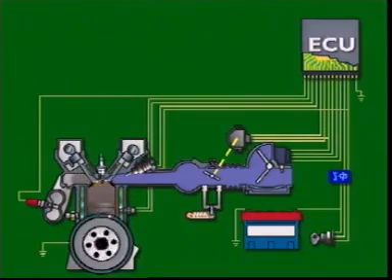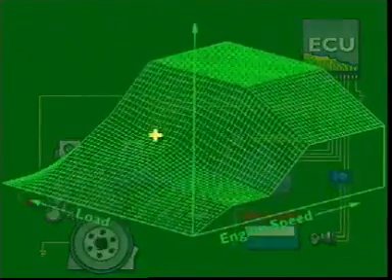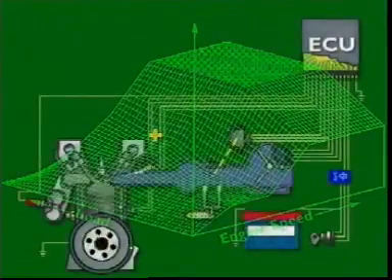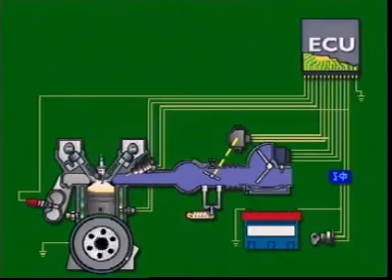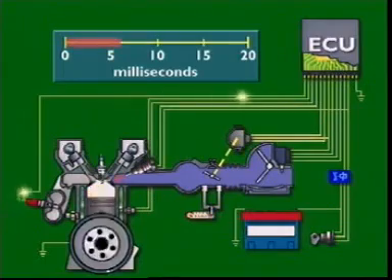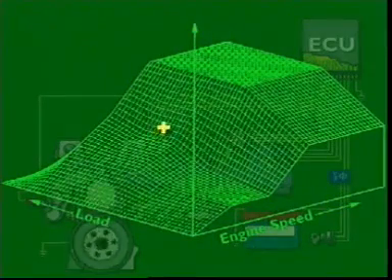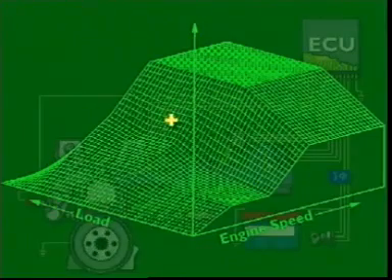This vehicle is using medium throttle with light loading and mild acceleration. Its control unit will set fuel delivery for a specified pulse width. However, if fuel pressure is less than when the vehicle was new, feedback from the oxygen sensor can cause the lambda control to increase injection time. The control unit learns the new time and stores it in its memory for future use in that condition.